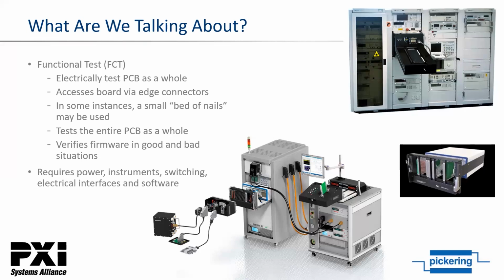Now, before we set definitions, let's be sure we're all on the same page. In this presentation, I'm talking about electrical functional test, or FCT. Basically, we're testing a printed circuit board called a PCB, or a subsystem like a field replaceable unit, or FRU, in an aircraft. FCT is typically performed during the last phase of the production cycle. The goal is to create an environment that provides signals and makes measurements from the connectors that simulates the system that PCB or FRU works in.